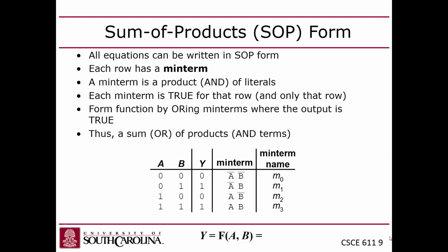Sum of products form means that you define the behavior of your logic as a sum of minterms, right? You guys with me? Sum of products. Now, what is the significance of that? Who cares? Well, the significance is you can define any Boolean logic function in this form.